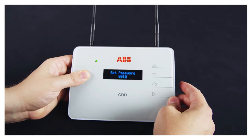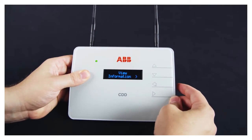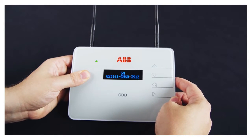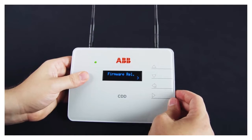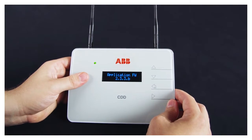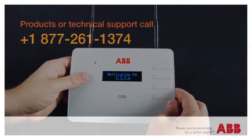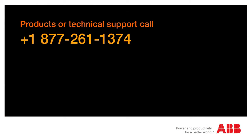Click Enter to advance to the next number or Escape to correct an error. Enter the password 0010 to access the advanced menu. Next, check the version of the firmware through the advanced menu under View Information, then Firmware Release, and then Application. If the firmware value is less than 2.3.3, contact ABB Technical Support.